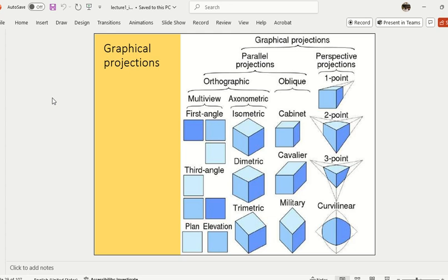So the plan by first angle method, where is the plan? Bottom, right? Plan is bottom. This one is supposed to be this side, and this one is supposed to be the left side. When you come here now, where is the plan? They switched the sides. In the first angle, plan became bottom, right became left, left became right. In the third angle, plan is the top, right is right, left is left.